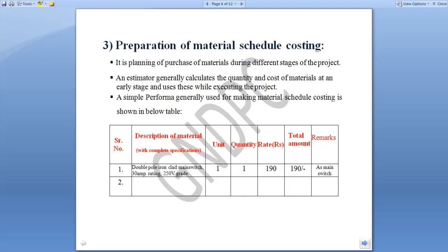The wiring is also done separately in a different wiring diagram. The material on the main board is further calculated, such as the main switch for the board, then the board for the main switch, wire required for wiring the main board, etc. Further, conduit or batten required is calculated on the basis of this particular installation plan only.